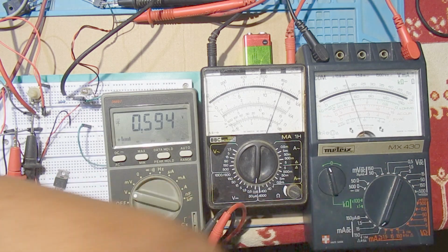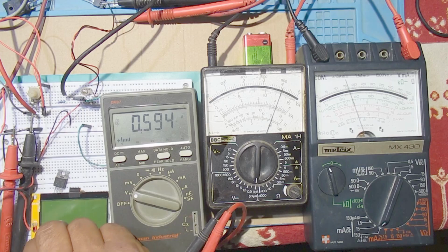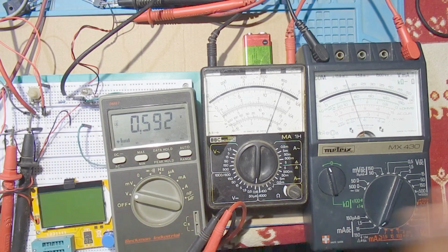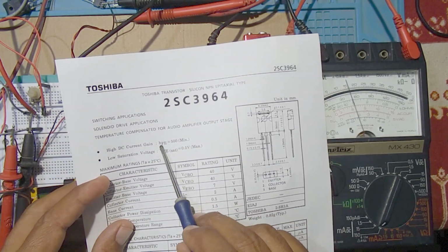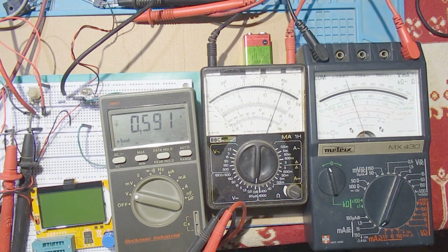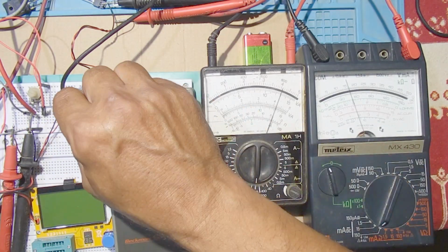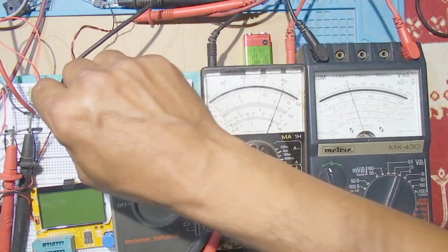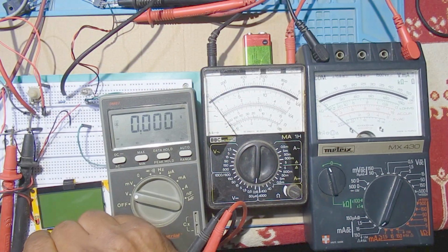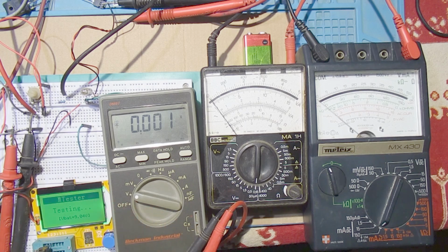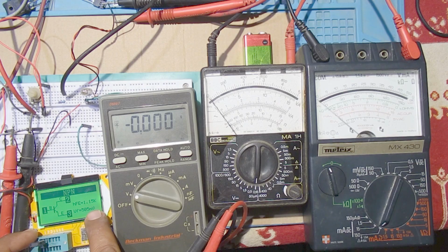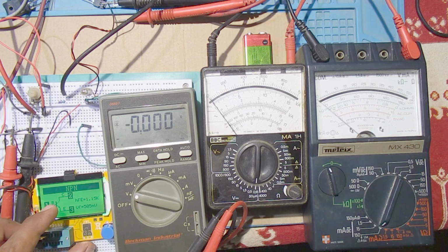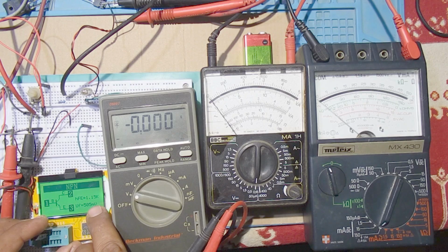I will measure this coefficient with this tester. I have the data sheet here. Here we can see that they said a minimum of 500 for the beta, the hFE. We found 1200. I will now close the circuit, turn off the circuit. I will measure this coefficient. We have 1.15K. So we are near our result, 1150.